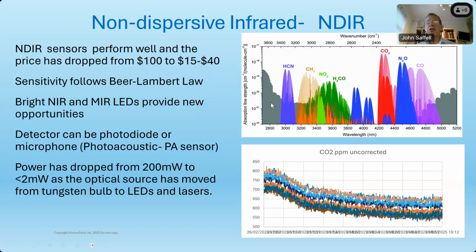And you can see here that NDIR can be used for a lot of different gases. Of course, the main one is the CO2 here in the blue there. That's the main. And whenever you worry about where is the water showing up, we have what's known as the 3 to 5 window where water isn't absorbing, because water will so dominate your signal. But that CO2 sits in a very nice area of no water absorption, and there's not a lot else around it.